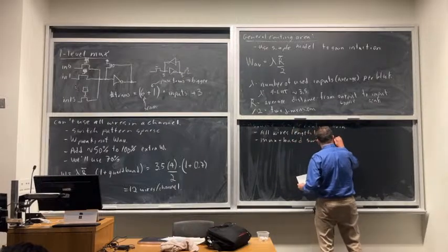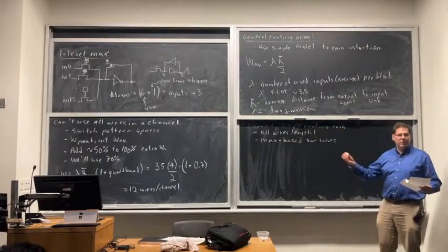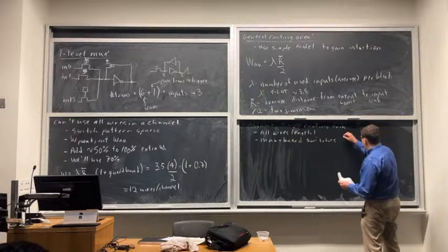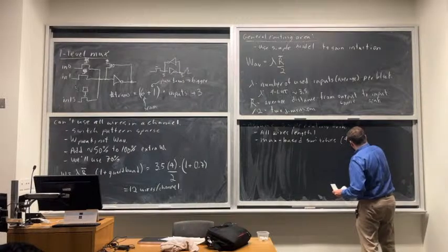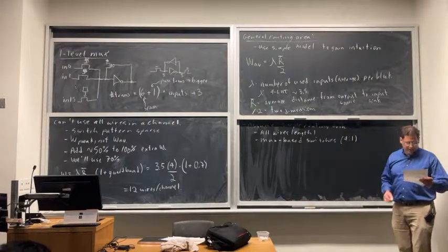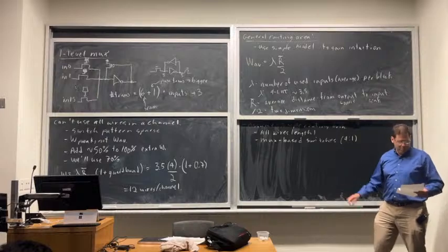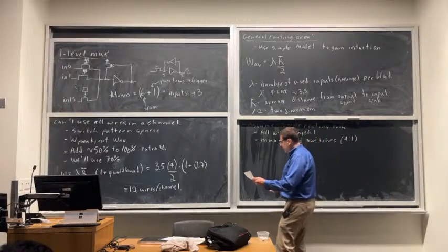Okay, so when we get to routing architecture, mux-based switches are dominant. That's the most common type. And we can make this work with 4 to 1 muxes. You could also make your muxes somewhat bigger. Both are reasonable, but this is a reasonable choice.